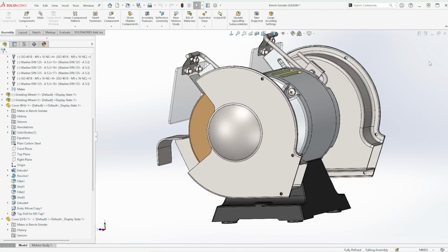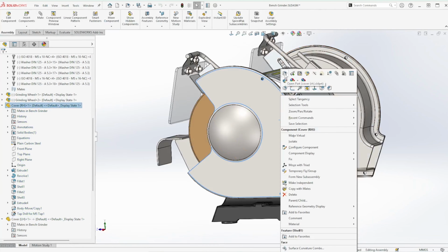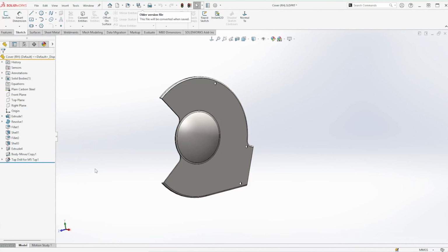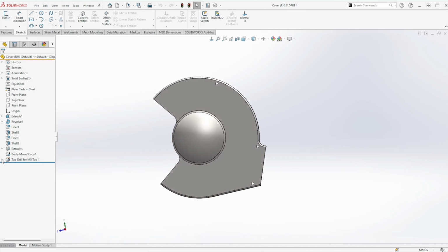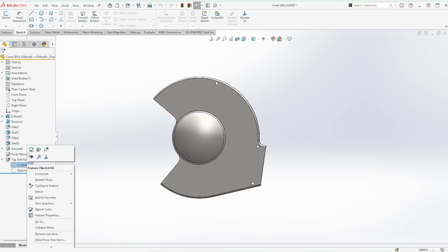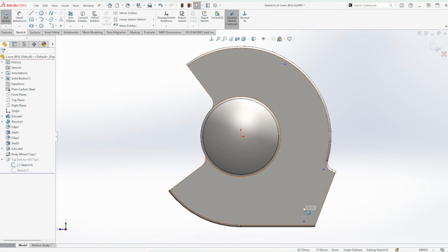But when I exit the part and I open it up in its own window, we don't have the external references. Instead, when I interrogate this sketch where the hole positions are defined, we have 3 underdefined points because what happened was essentially a one-time copy, a one-time transfer where the positions were pasted into this sketch, but they have no other definition.